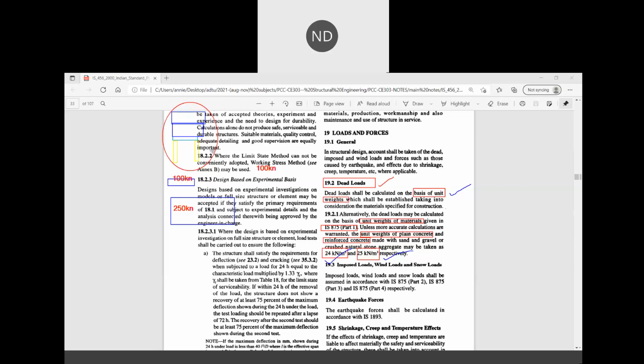Again, we are going to make it stronger if it is weak, or we are going to decrease it, and based on your estimation also, when we are designing we'll calculate the loadings. We will find out how much total load is going to come from this building, how much live load can be present. Live load means furniture, etc., or your movable loads, like human beings, animals, etc. Movable loads, how much is going to come, etc.